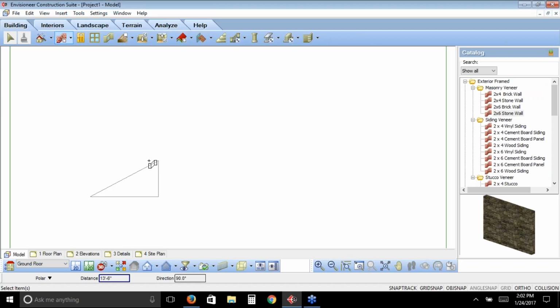When I use the Walls by Baseline tool, it's always going to hinge itself back to that original start point. So think of it as drawing by putting in a nail where you're first putting in your very first point, and every time you hit a corner, you're going to put another nail, and you're just kind of putting an elastic band around the area that you're outlining. So that elastic band is always going to stretch back to that very first point.